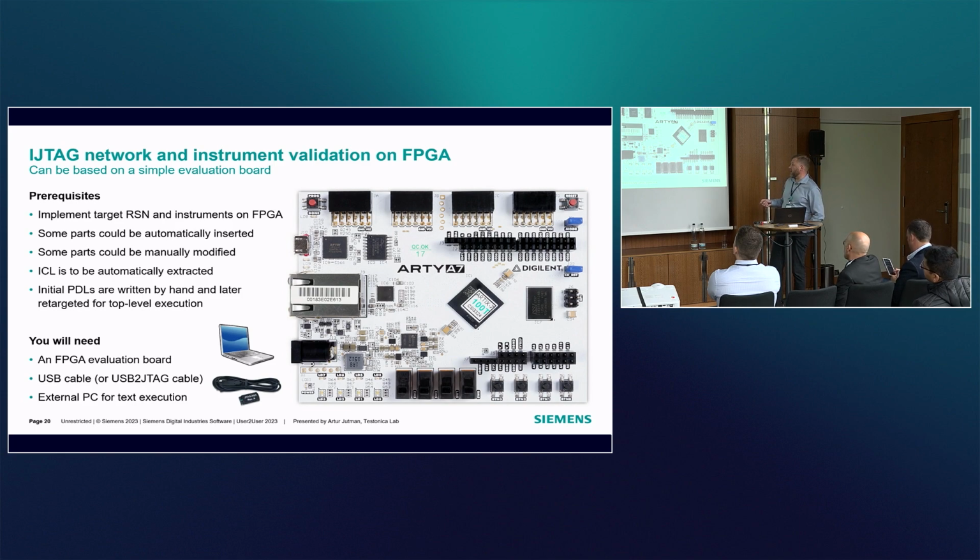In terms of preparation of the actual firmware for the FPGA, there are a number of prerequisites. If you want to work with arbitrary scan networks, then we need a way to implement both them and the instruments on FPGA. Some parts could be automatically inserted, some parts could be manually modified.